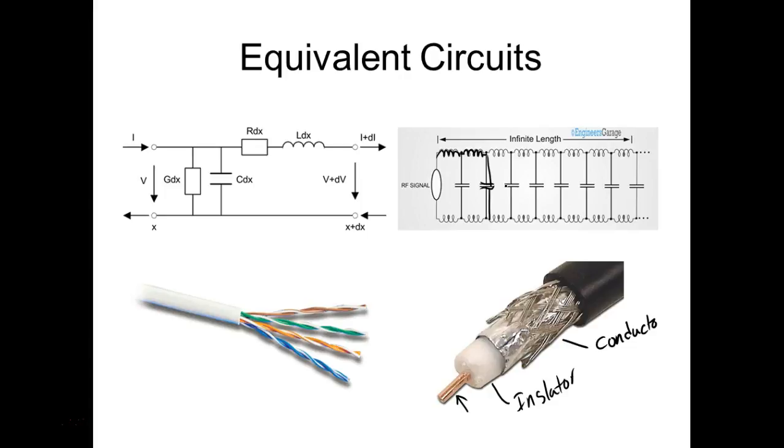Which is really cool. So if I've got a 75 ohm coax cable, that's its impedance. You cannot measure the impedance of a cable with a meter, because a meter puts out DC. Impedance is AC, right? You understand? So we can't measure the impedance of a cable that way. We had a little test jig that we set up where we would read the voltage and switch different impedances. When we got the maximum transfer, we would look at what we had set, and that would tell us the impedance of the cable. You cannot measure the impedance of the cable with an ohm meter. All you're going to do is measure the resistance of the cable.